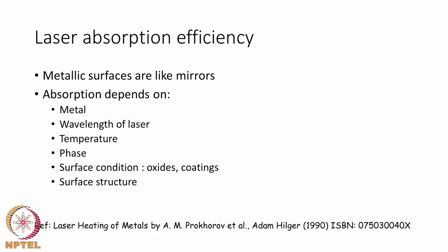The phase, that is the liquid state or vapor state or the solid phase, is to be known when we are applying the absorptivity of the laser. In other words, laser absorption parameter is going to be a function of either time or temperature as we choose to model it. The surface condition of the material also plays a role in the absorption of laser.